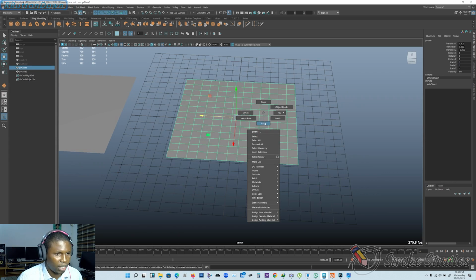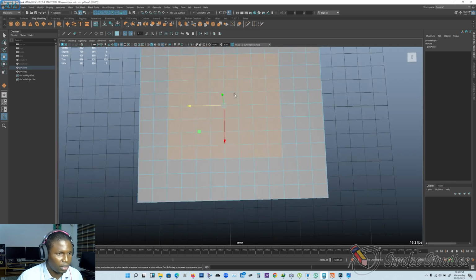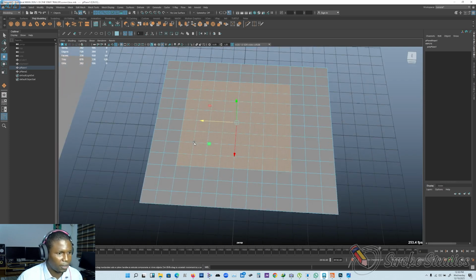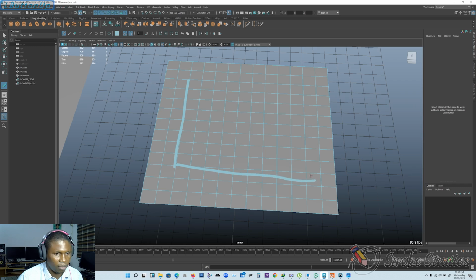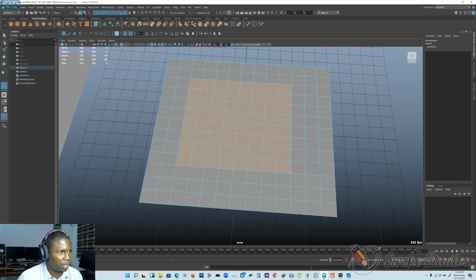The first one is I can select some amount of faces here and grow them. Okay, see how rectangular this selection of faces is. It's just rectangular. Now if I have all this selection and I go down to this option here, I hit Circularize.